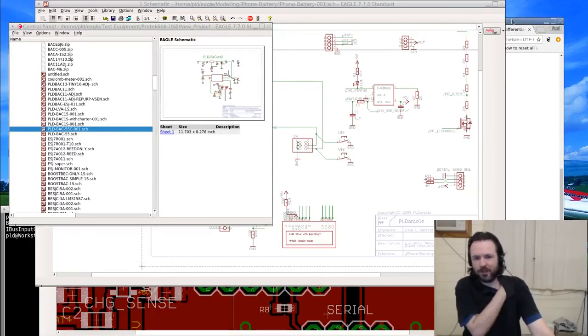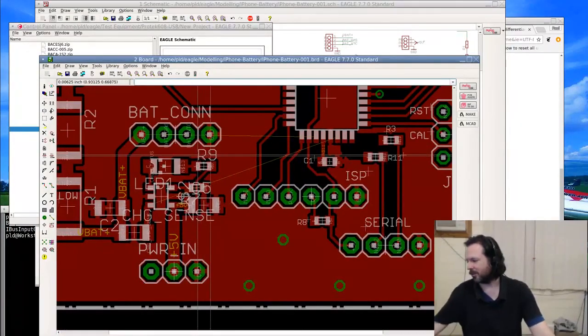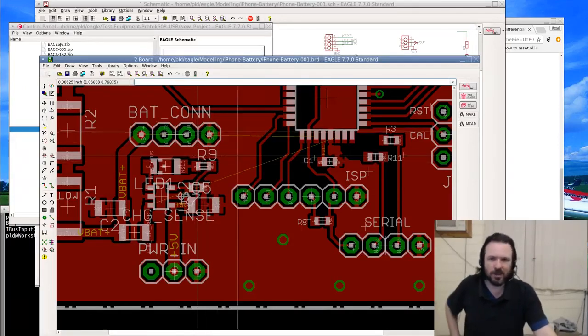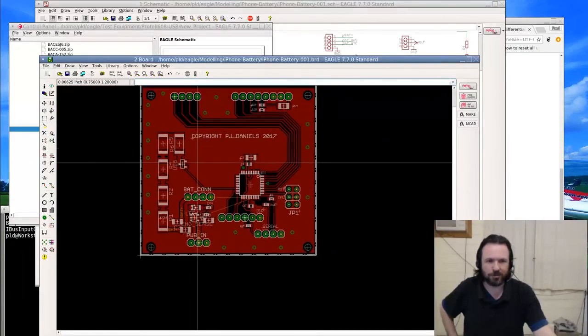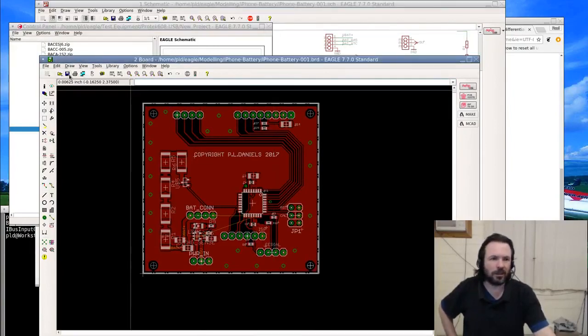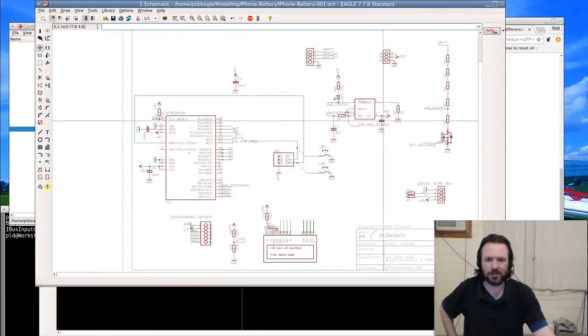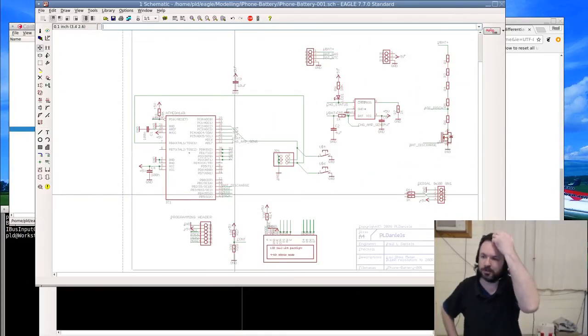I think for this particular task I'll probably have a 0.1 ohm shunt. So we're going to lose about 50 millivolts, I think. 0.1 times 0.5, yeah, 50 millivolts. So it's not brilliant, but that's well within the error margin of these anyway. So, alright, I'm winding down, my brain's fading out on me. I know I just need to sort out that current sensing and then I'm good.